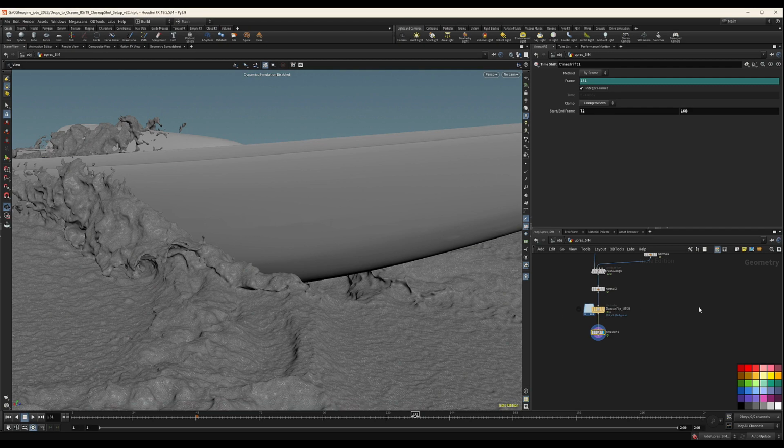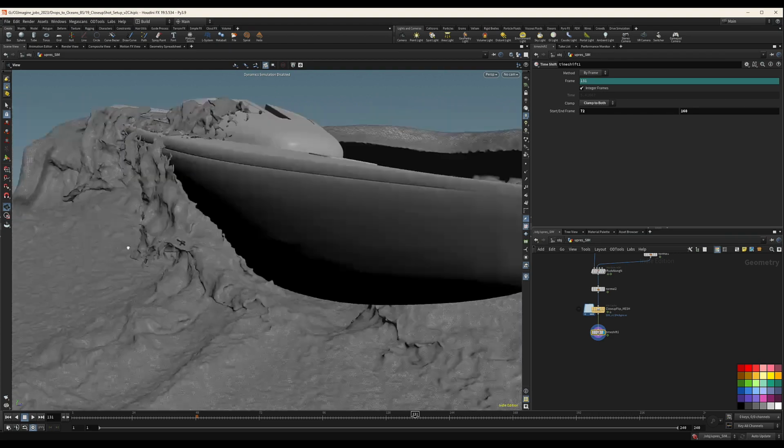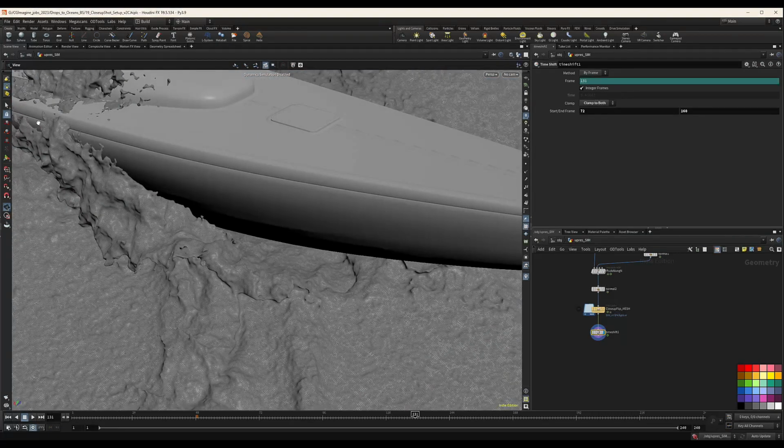So we're going to have the regular Whitewater, but we also want to have that at points based on the vorticity. So every area that's a very high vorticity area, I'm going to have a layer of Whitewater on top. That's going to help make everything more dynamic and blend the Whitewater and the surface better.